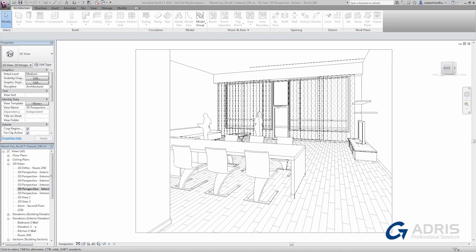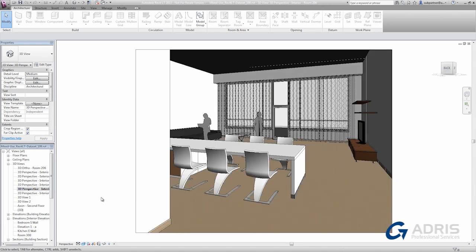But there are other ways we can display this view, such as a few different types of shaded view, and we call these visual styles in Revit LT. So down here on the view control bar, I'll click the small pop-up, and let's try shaded. Now as you can see, all the different surfaces shade with various colors assigned to their materials.